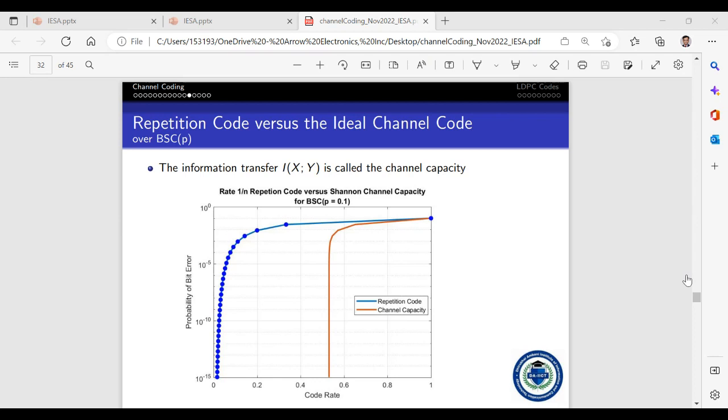Because polar codes are better at approaching the orange line, even when the data size is small. If you're transmitting large data packets at a time, maybe you're doing some video transfer or image transfer, and you can send at a time maybe 20,000 bits or 64,000 bits, then LDPC codes are fine.